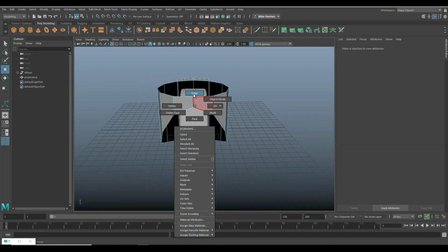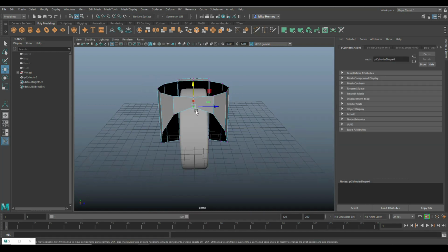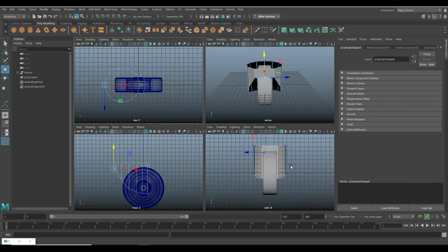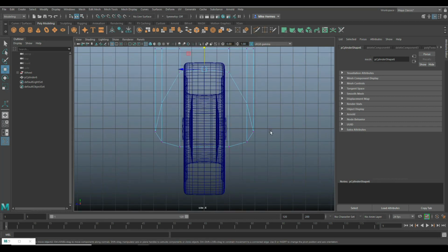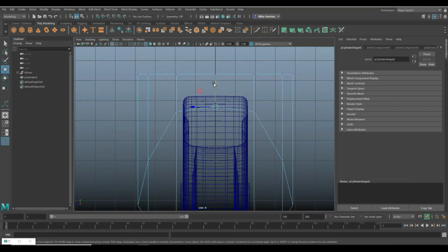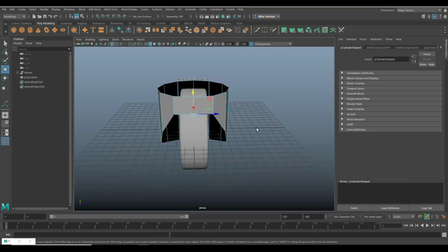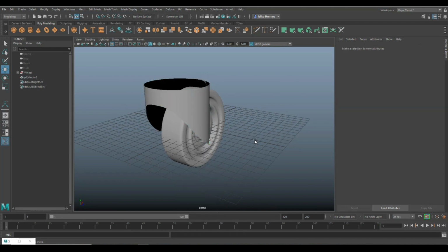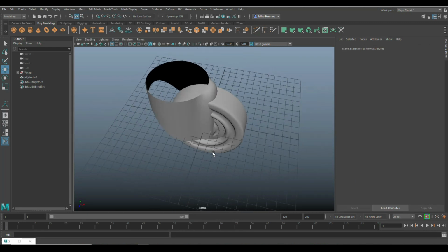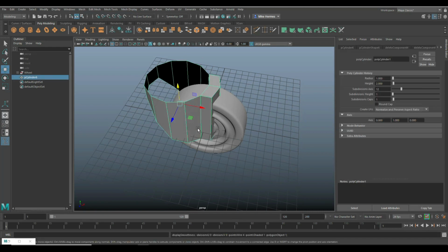We just want to go in here to vertex, drag click this guy, and bring that down, preferably straight. Doesn't have to be 100% straight. A little arch there might be cool. So there you go. We're going to hit 3 to preview smooth to have a look. Starting to get there. We're going to hit 1 to go back.